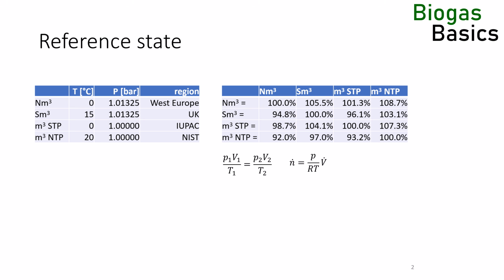The calorific value of biogas or methane is also given at a reference state. Methane has a heat of combustion of minus 891 kilojoules per mole at 25 degrees Celsius, 1 bar. 3 significant digits is about the accuracy to which a calorific value can be measured. Most standards define calorific values with more digits, but these numbers are definitions, not measurements.